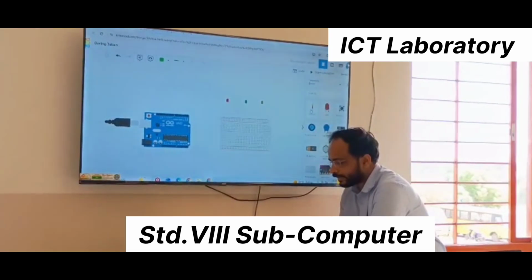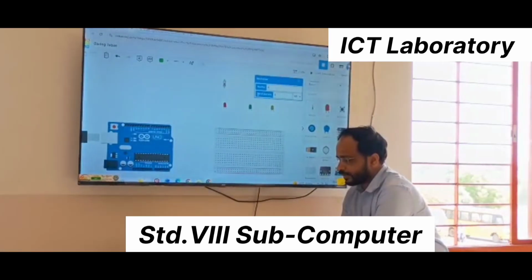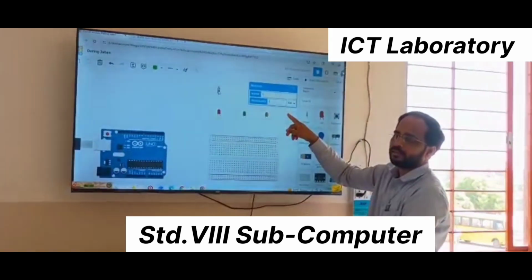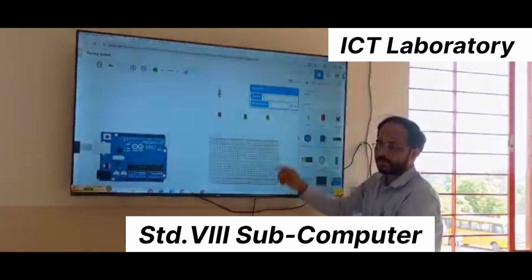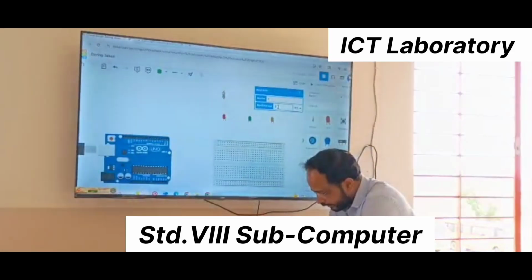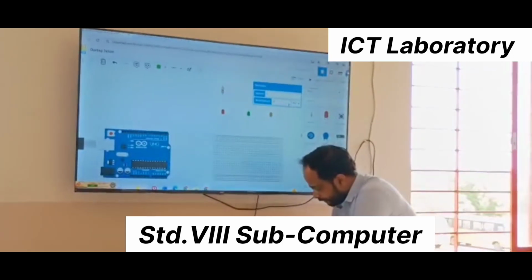Afterwards, you have to take a resistor to make the connections. But the condition is for resistors, you have to change the resistance to 220 ohm. By default it is 1 kilo ohm. You have to change this value. How to change this? You just have to click on that number and you can edit the number and change this unit also.